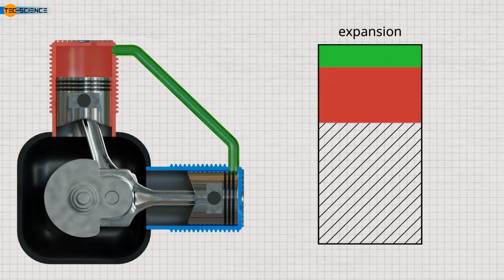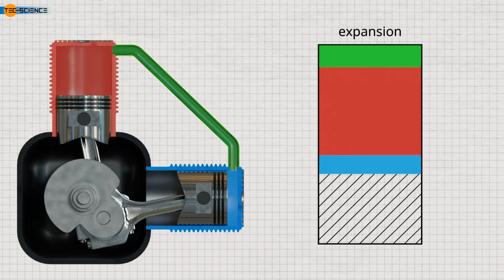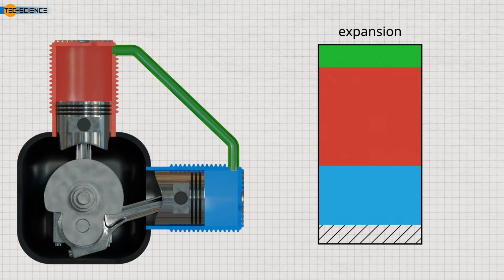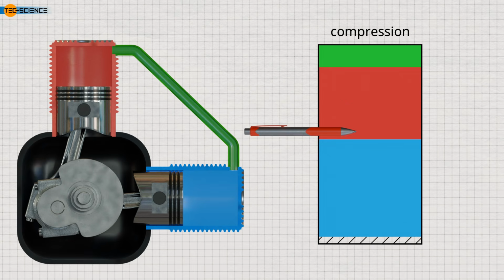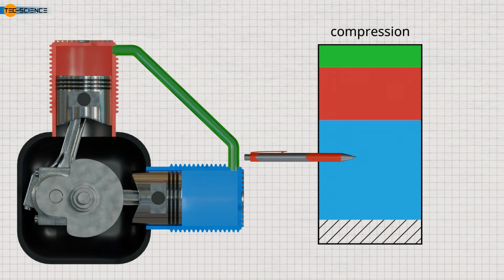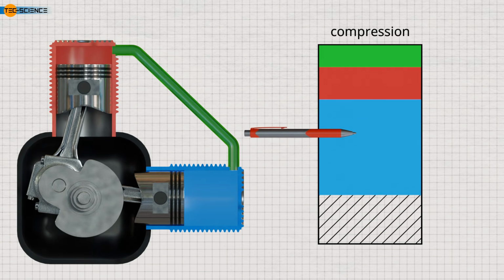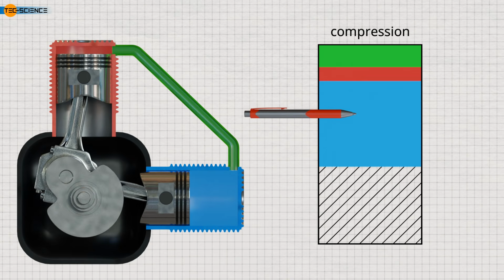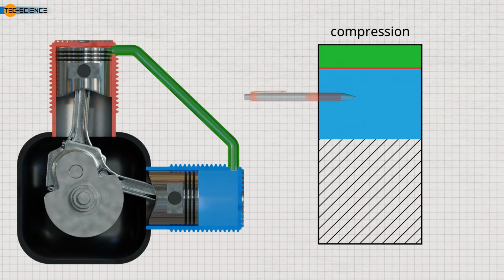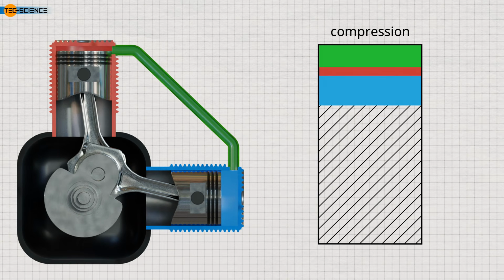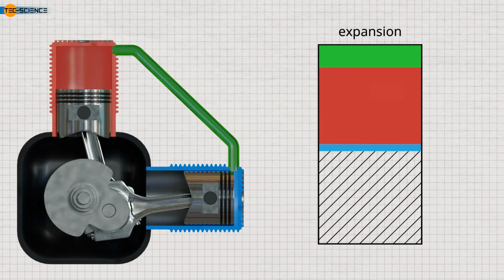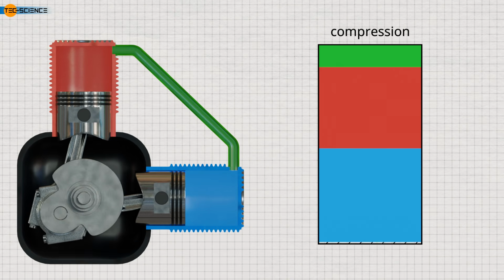During the next half turn of the crankshaft, expansion is reversed to compression and the opposite effect occurs. The volume of the heated cylinder now decreases faster than the volume of the cooled cylinder. As a result, there is more gas mass in the cooled cylinder than in the heated cylinder. The pressure during this compression process is therefore relatively low due to the relatively large proportion of cooled gas. The compression work done on the gas is correspondingly low.